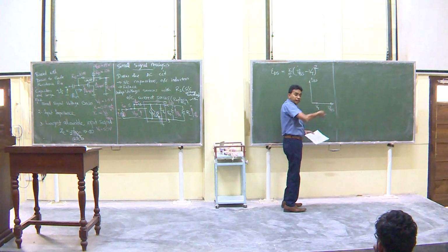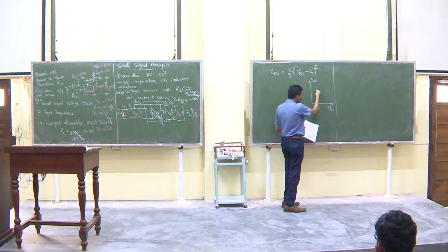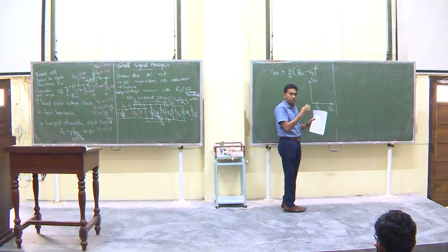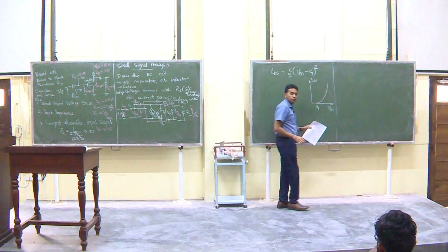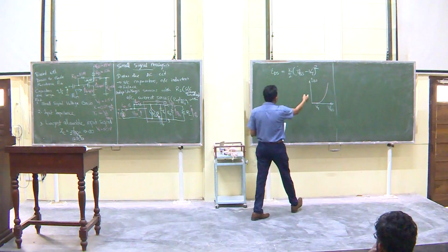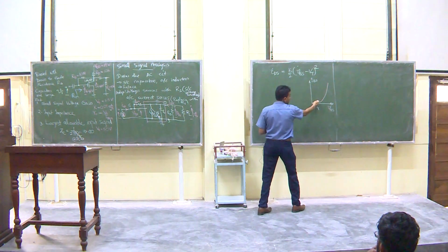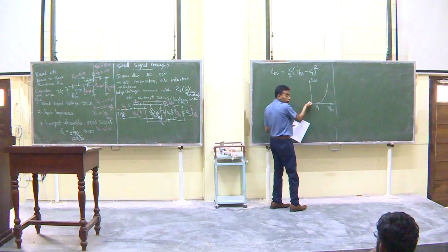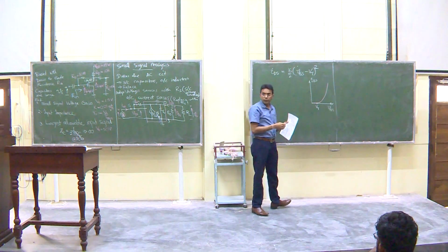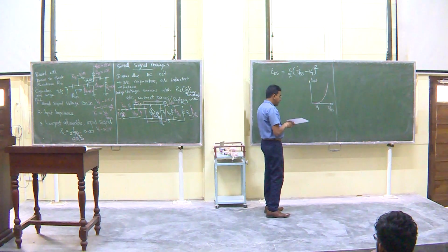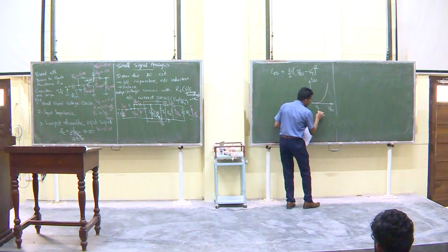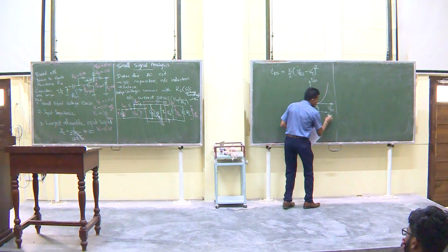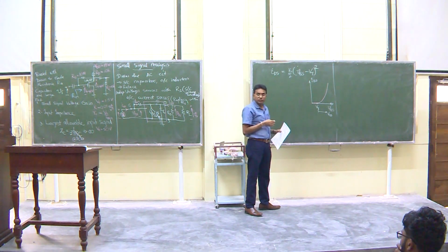From there on you have a quadratic relationship between that voltage, which is basically, if you draw an axis here, whatever the voltage here is the V overdrive. VGS above VT is the V overdrive, right? So that's a quadratic relationship. So that's basically the equation that is governed by this from here on. Not for the cutoff, but for the saturation. Okay? So it looks like that. So this is VT. Any voltage from here on is V overdrive. That is VGS minus VT.